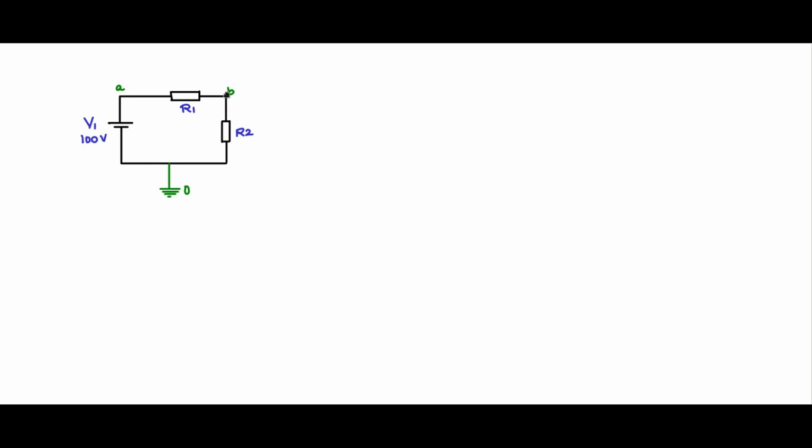This simple attenuator circuit, we have seen how we go about simulating in Ngspice. In this session, we will introduce one more component. We will see how we invoke models, subcircuits, and refactor the .cir file into subcircuits netlist and .cir file.